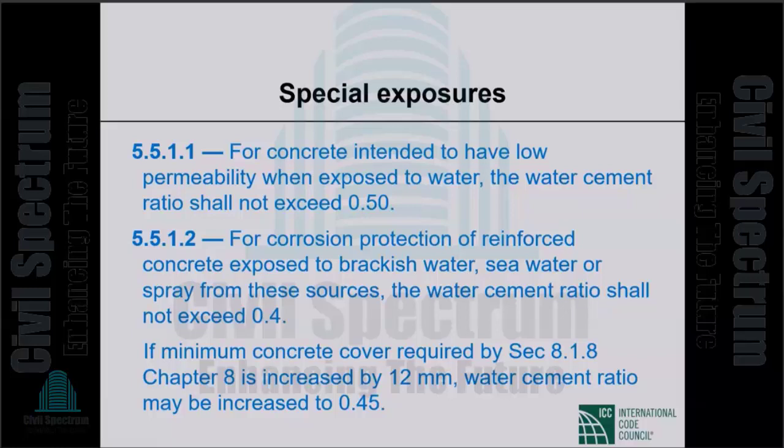So sulfate resistance, corrosion protection, and permeability or lack of it, impermeability. Those are the three considerations. So BNBC is starting with watertight concrete, intended to have low permeability when exposed to water. And what you need to do is to keep the water cement ratio. Today it would be the water cementitious materials ratio. I think that's the way you should practice it, because that's what makes more sense.